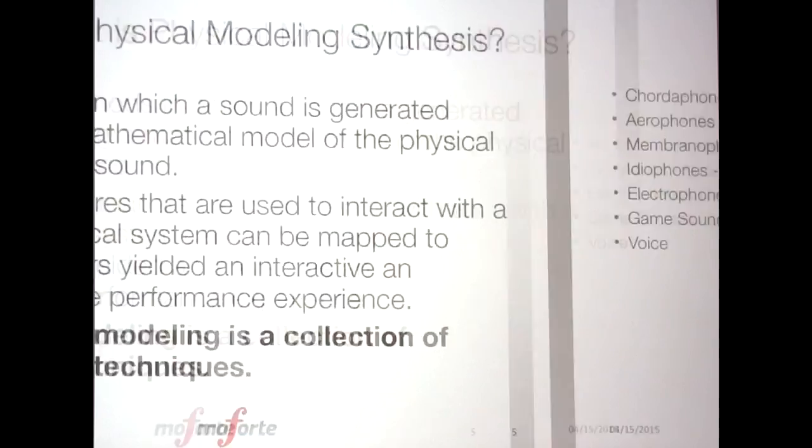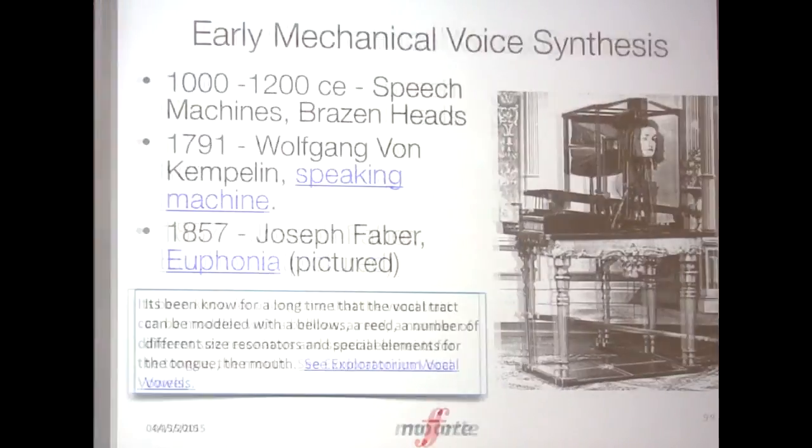Go ahead. I just wanted to say one of the problems with the human voice is a string, so it has all the harmonics, but it's really got multiple filters. And so it's really like a string played through multiple wah-wah pedals. And there are some of the earlier modeling techniques, like the linear predictive coding, which is an attempt to reduce the amount of information needed to reproduce the voice. It characterizes the transitions between the center frequencies of the different filters, of the 2 or 3 filters that the mouth uses when it shapes essentially the single pitch of the vocal cord.